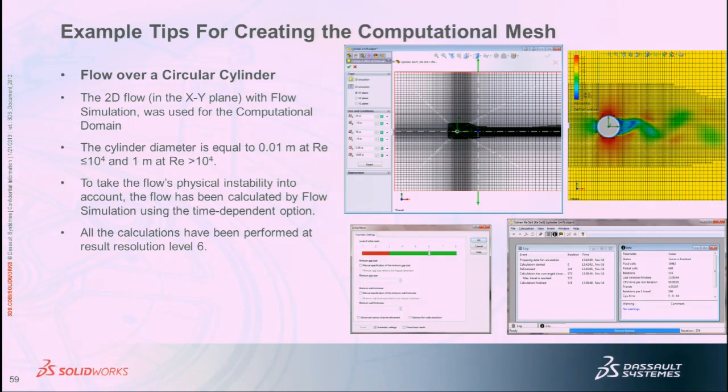Now as you go up, there's more refinement done. What it's looking at are gradients in the solution, where temperature, density, velocity, pressure, where there are high gradients. It runs the solution 30, 40, 50% of the way towards convergence, and then it automatically stops, and it searches all the cells, and wherever it sees a large gradient across the cell, it goes back and further refines that area, and then it restarts. It's all done hands off, the user is not involved in it.